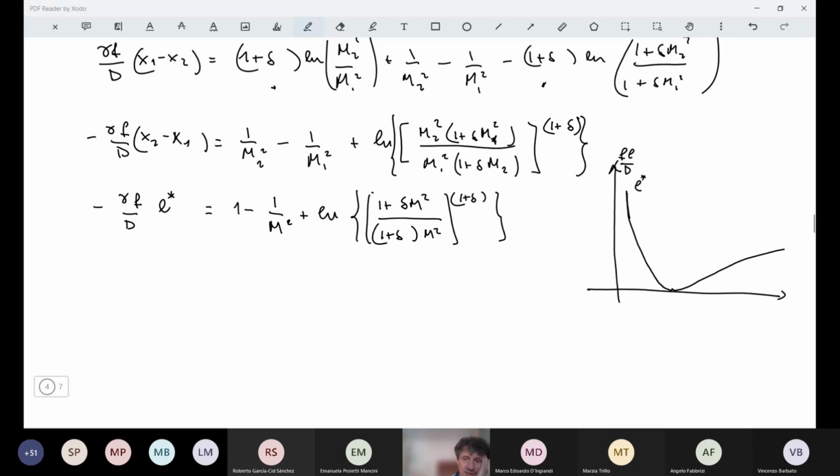This is f L star over d. This is the Mach number. You have 1, and here you have 0. So the allowed length will be 0 if you start from Mach number 1. If you are in the supersonic or subsonic regime, for instance, here you can have all the lengths which are less than the critical one. So we have no solution here. Note that this would reach an asymptotic value in case of a high value of M, and this asymptotic value will depend on gamma, and you can see it's between 0.8 and 2 for ranges of gamma between 1.1 and 1.4.